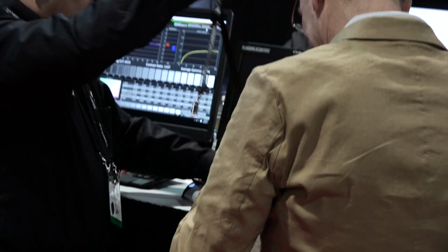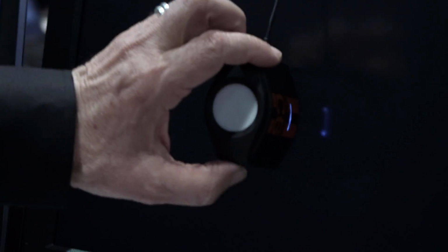So the C6 is a... Let me shove you aside rudely. Sure. The C6 is OEM from X-rite. They manufacture it for us as like an i1 Display, but we put additional features into it, including we characterize it on a wide variety of displays, so that there's a table in our software that you can select to say this is a white LED backlight, or this is an OLED, and you can get much more accurate that way. I see. We also have additional low light handling, so we can read more accurately down in the darks.